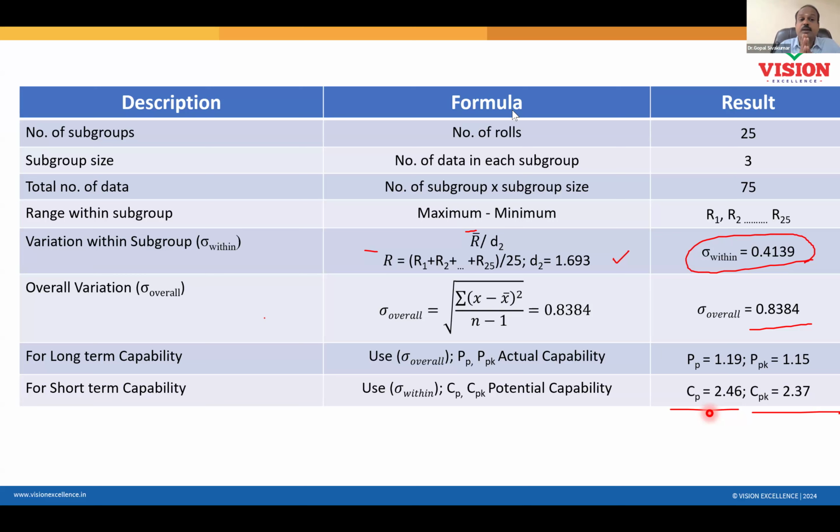But at least what you can do is dictate to them how the sample must be collected. Yes or no? Suppose you have dictated to collect samples for the last 7 days of production. And if the data is available and the report is giving very convincing values for both Cp, Cpk and Pp, Ppk, before trusting the Cpk as well as the Ppk, you must ask for their control charts. You must ask for their control charts.